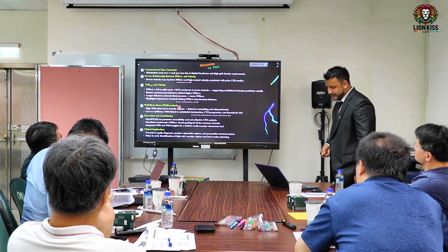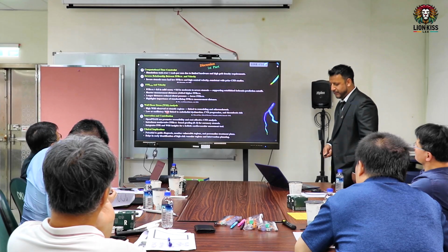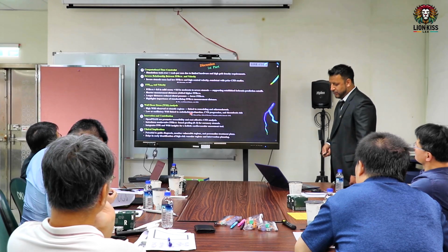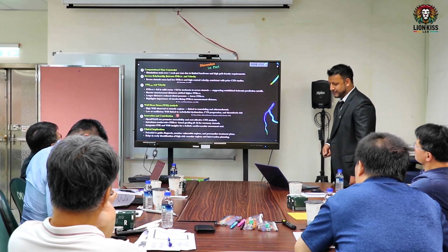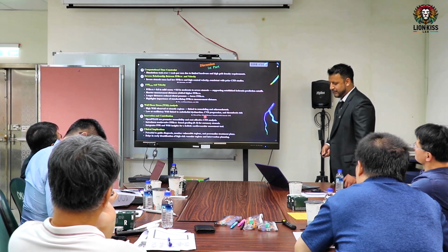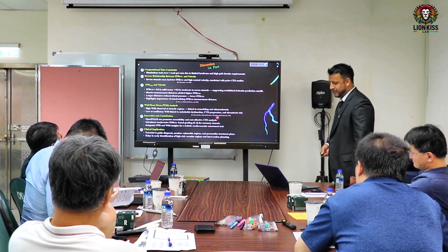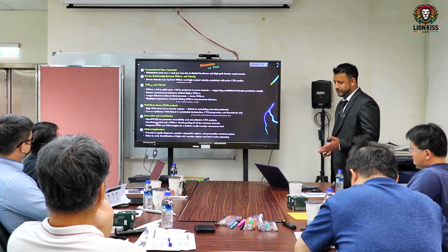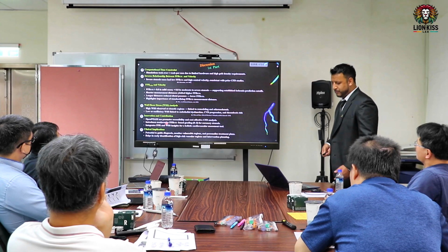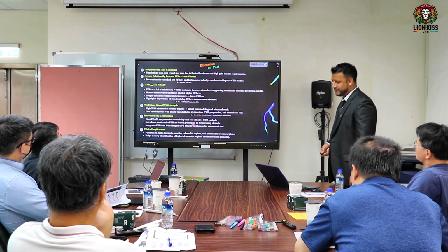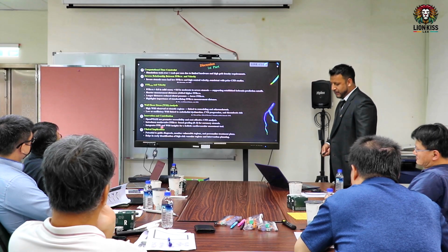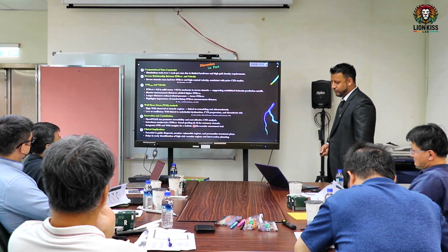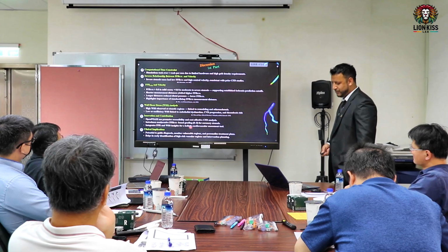For wall shear stress analysis, high wall shear stress was observed at the stenotic region, linked to remodeling and atherosclerosis. Low and oscillatory wall shear stress is linked to endothelial dysfunction, CVD progression and thrombus risk. Innovation and contribution: in the first part we used open-source software to promote accessibility and cost-effective CFD simulation, and introduced non-invasive FFR based on a grading of 0 to 5 for coronary stenosis.